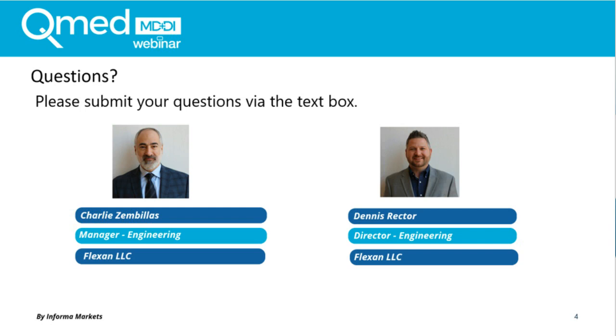The fecal catheter. Yes. The challenges with that particular application were just keeping the lumens open due to the thin wall on that extrusion when it was such a large diameter. So we had to incorporate some methods using our pneumatic shop air that would allow us to keep the profiles open while we were extruding. It's a little non-conventional application.